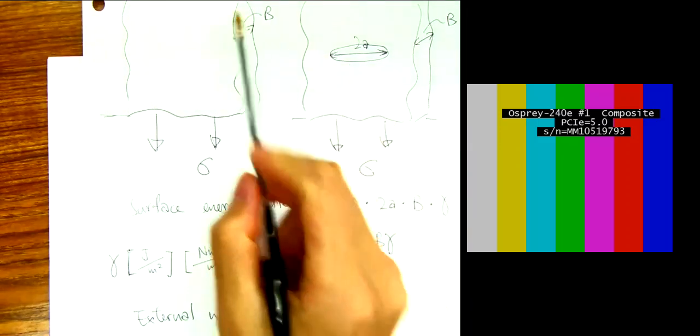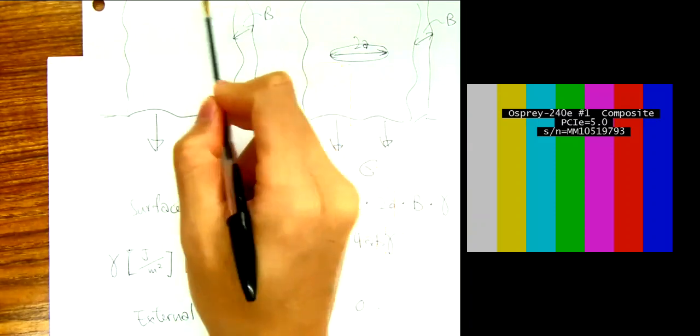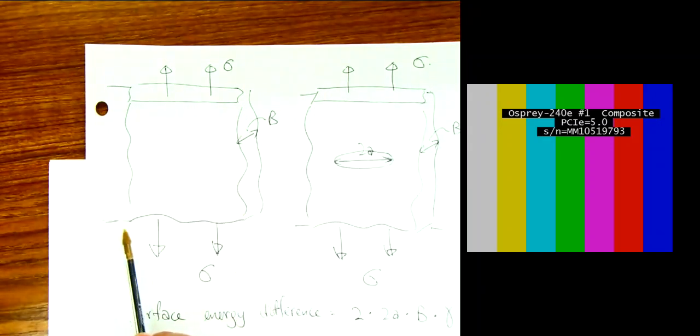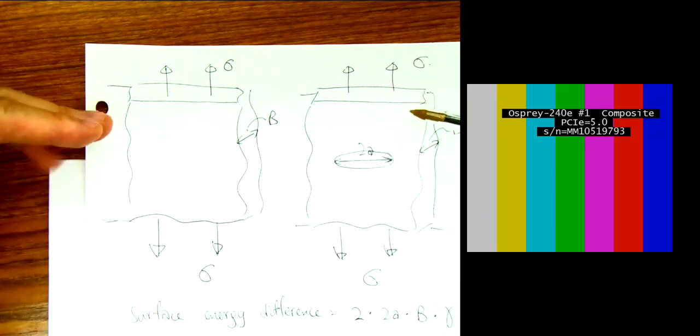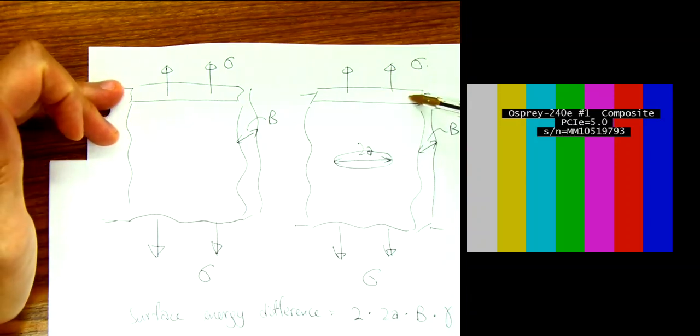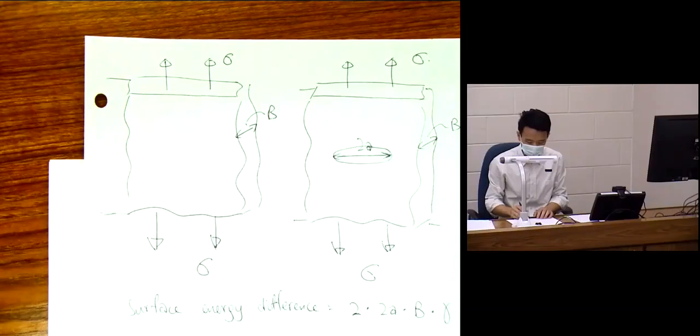That's because once we reach a stress of sigma, we fix the loading grips so they do not move, right? So we do the same for these 2, and they undergo the same amount of displacement to reach sigma, and then we stop there for both of them, and therefore there is no difference in the work done between the two configurations, and therefore it is 0.